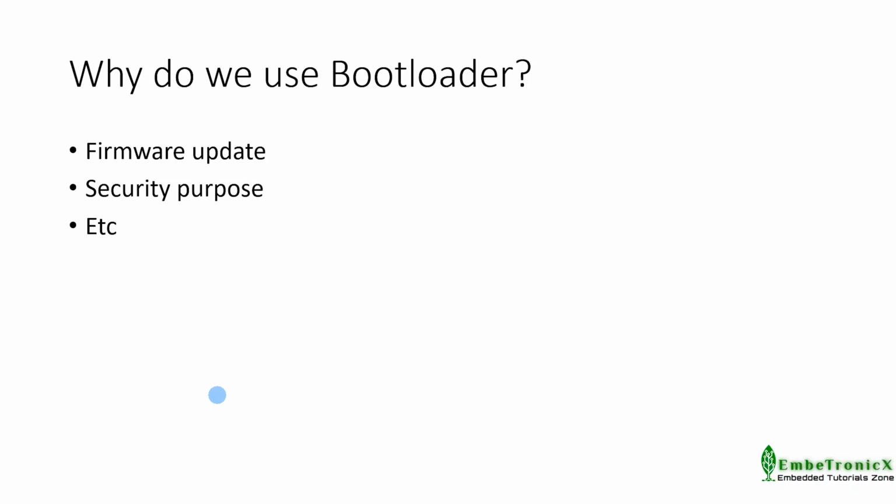The next use case is security. If you are making some secure products, then the bootloader can check the application CRC every time during the boot. If someone has changed the application or it has any memory corruption, the CRC verification will fail and we can take the necessary action. Like this, many other use cases are also there.